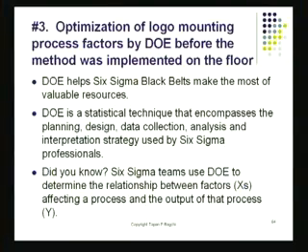The third thing is, I should have actually optimized the mounting process itself. There again, my old friend design of experiments, DOE, comes along. There I have these different process factors that I can play with, and I can construct this matrix. With the help of the matrix, I may be able to conduct certain special experiments that will lead to an optimum process. Because here, each of these process factors that are made to work together would have been set at their optimum levels. This discovery, of course, would take place through DOE.